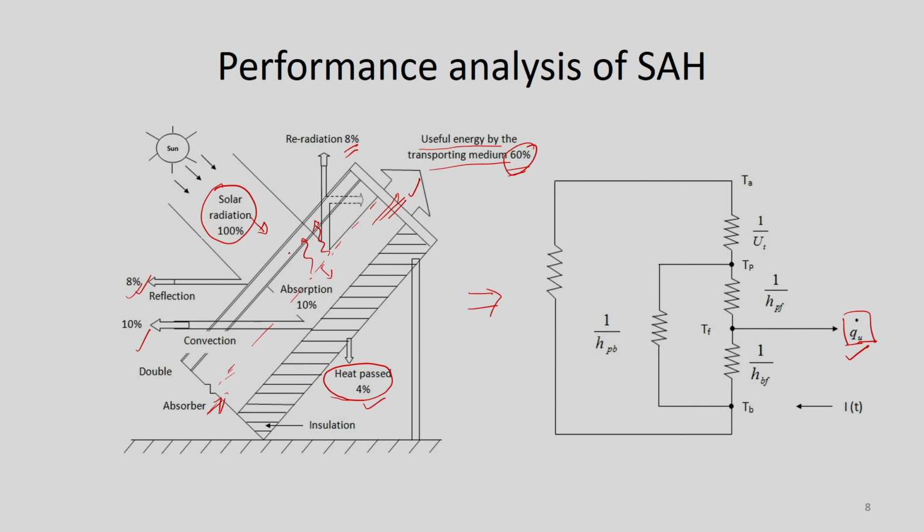The radiation transmits through this glass cover, it is received on the receiver, and again heat exchange will be there between this absorber and this back cover. When heat exchange takes place, some amount of heat will be absorbed in this plate and this also contributes to increasing the temperature of this incoming fluid.